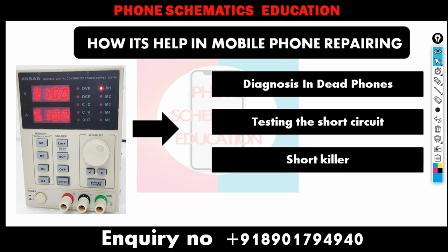Now next, short killer. A DC power supply is also used as a short killer. Through a DC power supply you can find which component or which IC is shorted on a motherboard, with the rosin method or the thinner method. For removing the short, it's also used.